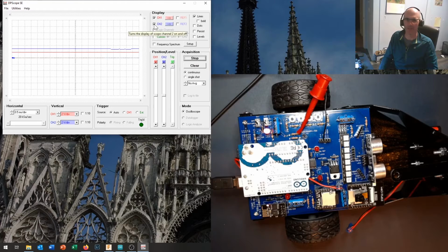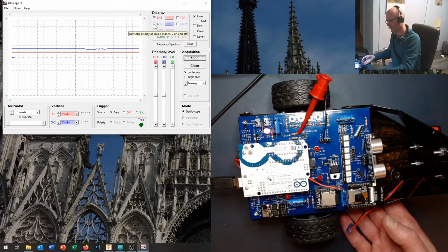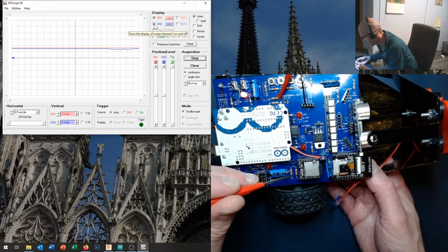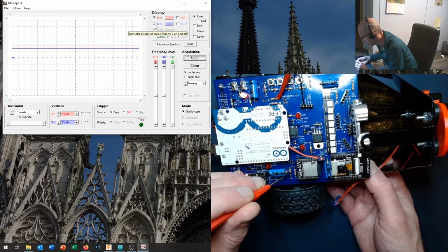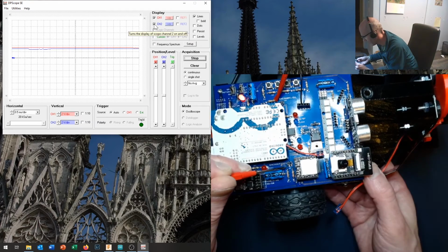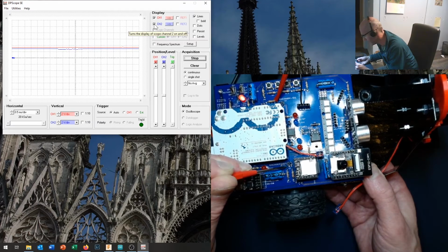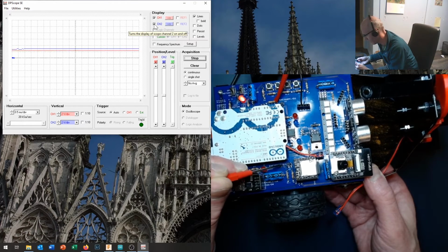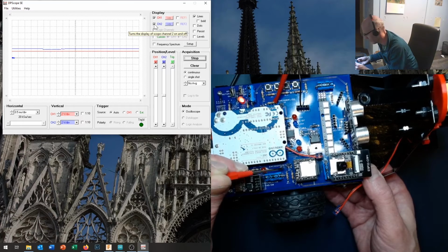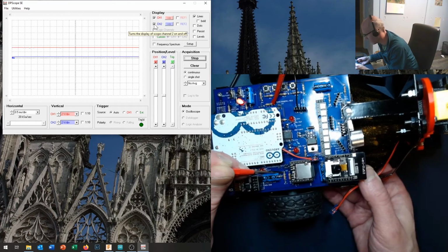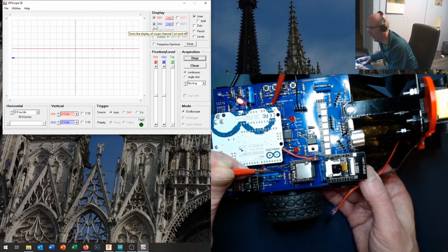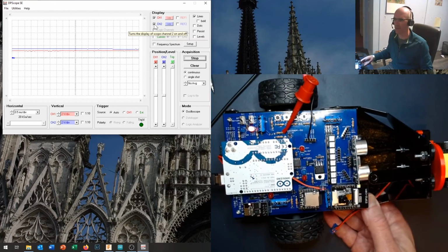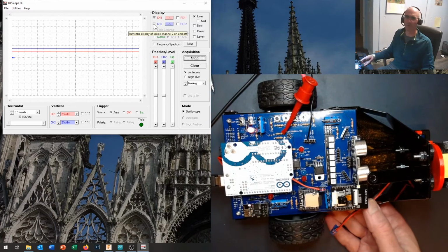Now, right now I'm not using channel 2 for anything. If you did want to use channel 2 for something, the equivalent place where you'd hook it up would be over here on R11, which is also a 10K resistor. And on R11, for the right side of the robot, you can see a little trace on the printed circuit board comes right down in here, connects right there, and then goes back to the Arduino in there. So you could connect on the QRD 1114 side of R11. Okay. So we can sample either encoder, and we do want to make sure that they're both working nicely.